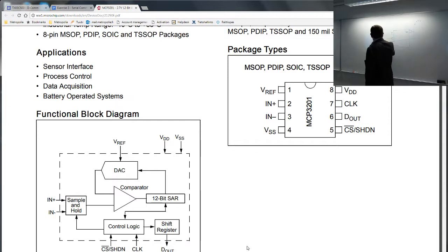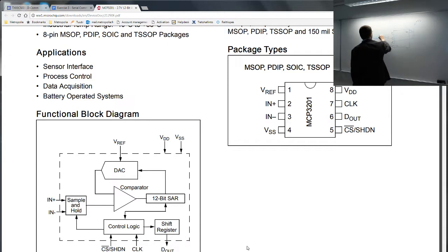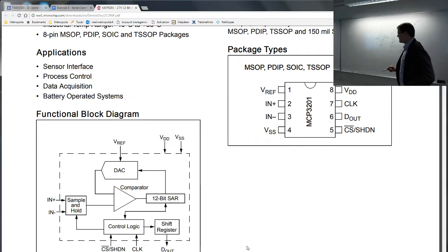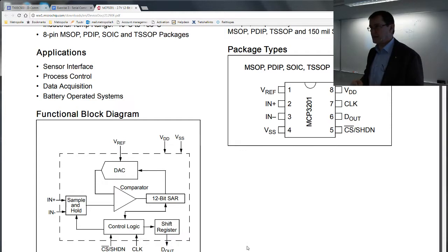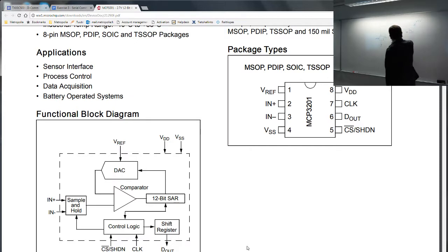Then this is your input signal, and since we have that LM35 analog sensor, that's just a fine signal source. So then we have 10 millivolts per centigrade here. Okay, and then it also needs some power, so from +5 is just fine. And again, remember to check a couple of times before connecting, not to destroy that LM35.